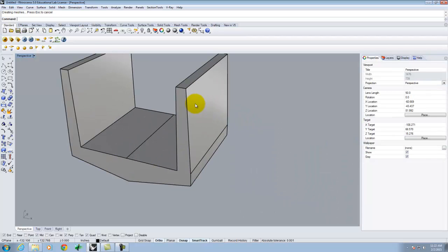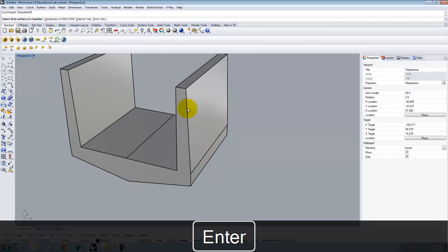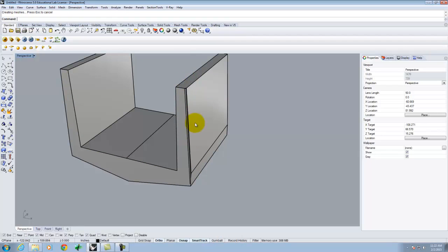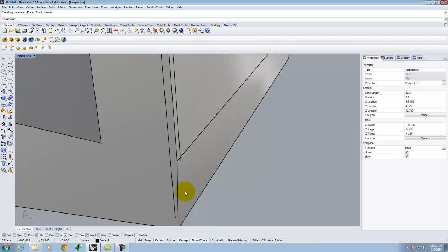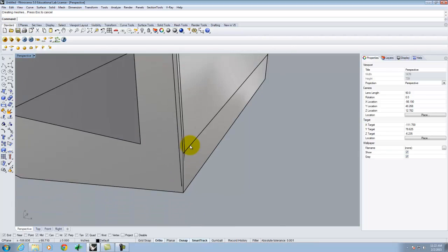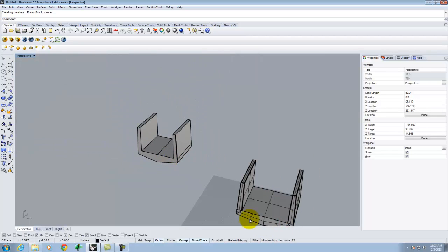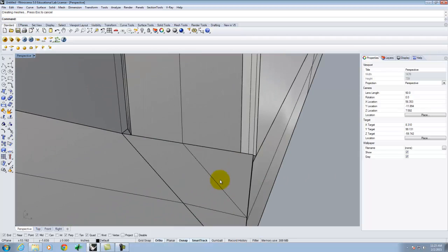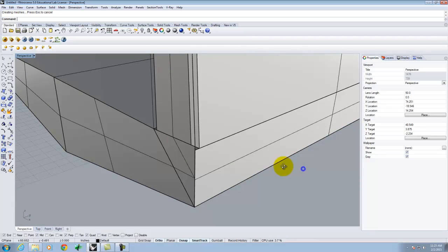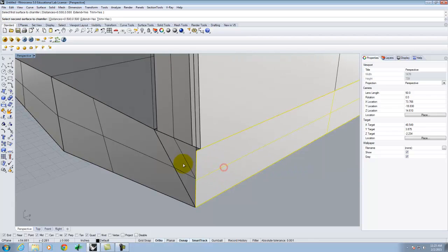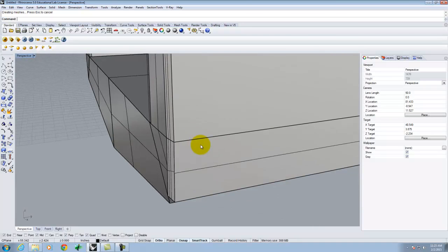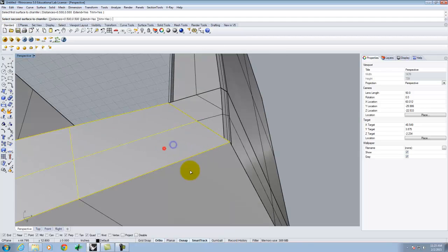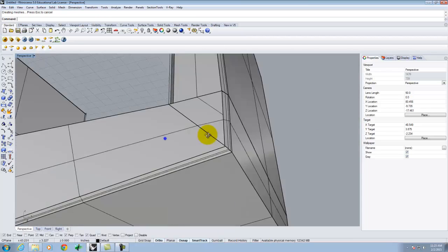All right, so if I did it here, chamfer surface, I could pick here and there, right? Now the problem is, because this is one solid surface, see how this edge kind of tapers down and gives me a funny edge? I'm going to have to do some manual cleanup to that, where when I built it this way, if we look down here, see how it stops at that triangle because I built the surface in separate pieces. So now if I were to do the chamfer surface here and here, it matches up much nicer without having to do cleanup. So there's a give and take in strategy, right? Likewise, this bottom is one of the most challenging pieces for how those come together.